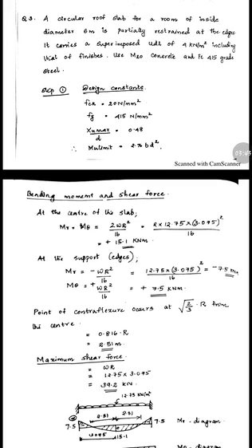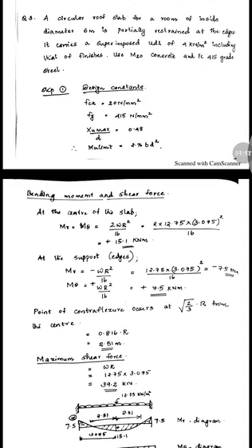After getting the load calculation, why are we not going for the finishing loads? Because in the question itself it is given that it carries a superimposed UDL of 4 kN per meter square, including that of finishes. Therefore no need of taking extra finish loads. So this 4 kN per meter square includes finish loads also. So this factored load is 12.75, and